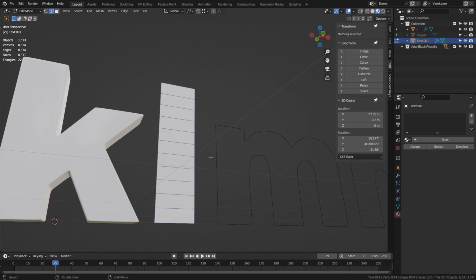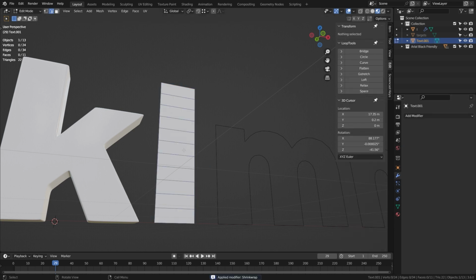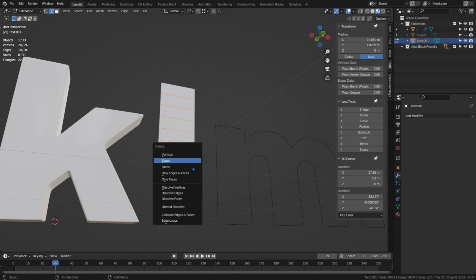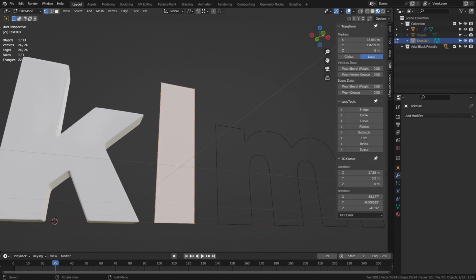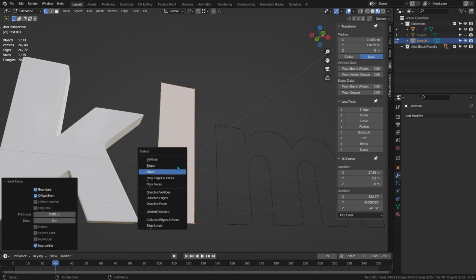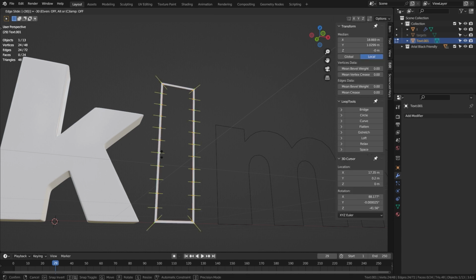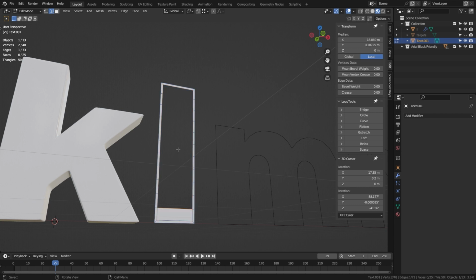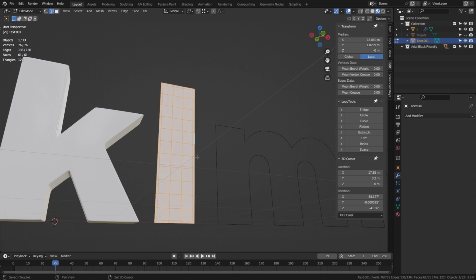And that's done. Go to object mode, apply the shrink wrap modifier. Back to edit mode. Press A, W, Control I, and then X, and choose edges to clear it all out. F, I, 0.001, X, faces. Alt and click inside. GG, Alt, -30, enter. Edge select mode, fill in those faces. Add 2 internal loops. A to select everything, Shift and N to recalculate the normals.